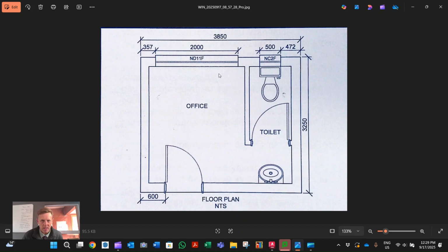And then I'm going to subtract the length of an internal wall. So I'm going to go minus 100. Half the length of an internal wall, which is 1,344. So from that point there, this line here, the outside edge, to this line over here, which makes the outside edge of that toilet wall, we're going to go 1,344 on the offset.